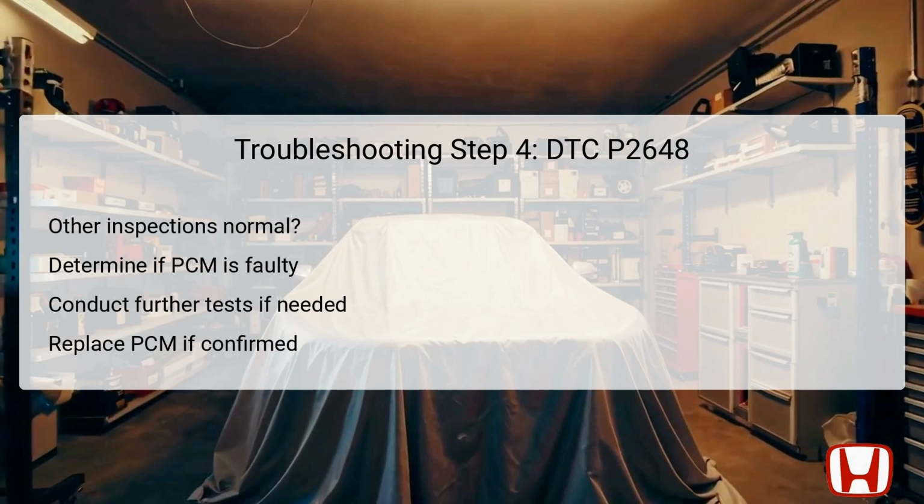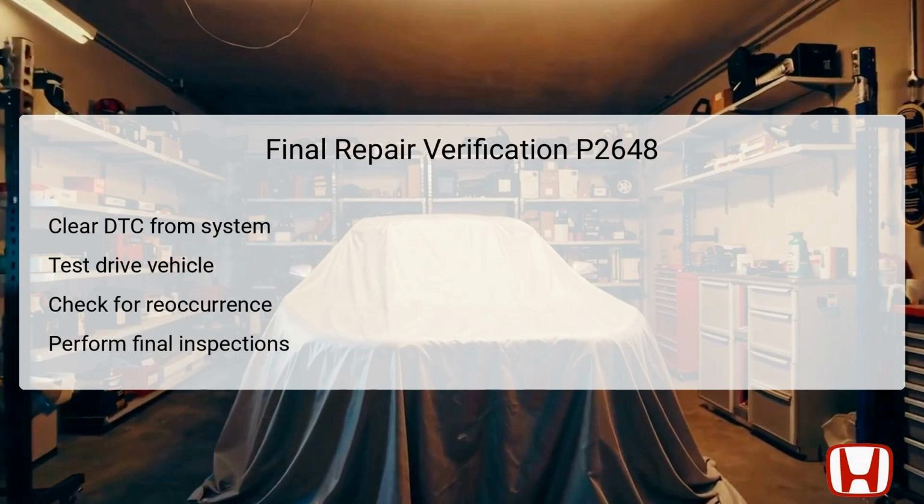This step reiterates the importance of thorough diagnostics to avoid unnecessary component replacements and ensure that repairs are both efficient and effective. After performing the necessary repairs associated with DTC P2648, it's important to verify that the repairs were successful. Start by clearing the DTC from the vehicle's system to reset the diagnostics. This process is usually carried out using the HDS tool.